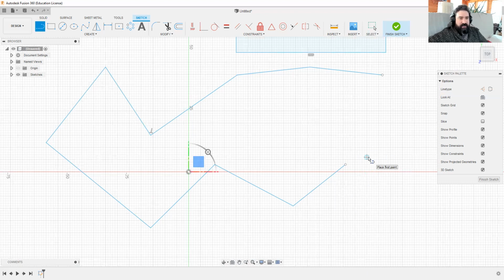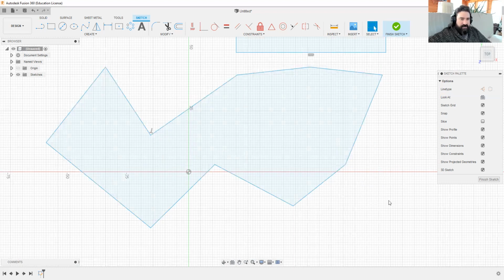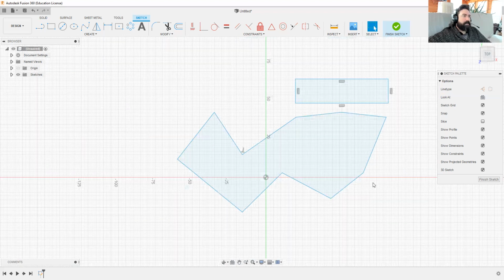But I'm going to repeat the line tool. That's just the line tool, not repeating the last line. Now I can go select that one and that point. Now that it's enclosed, I'll hit escape to cancel out of the tool. Now that enclosed that whole space and it turned blue, showing you that's a closed shape. Cool. All right. Center circle.